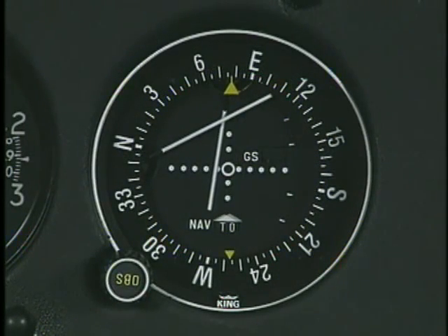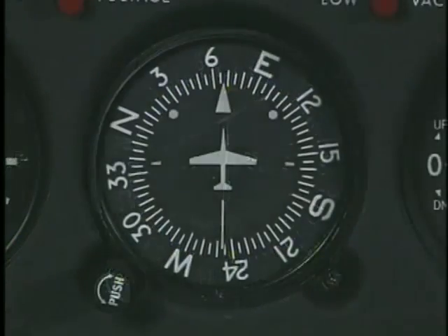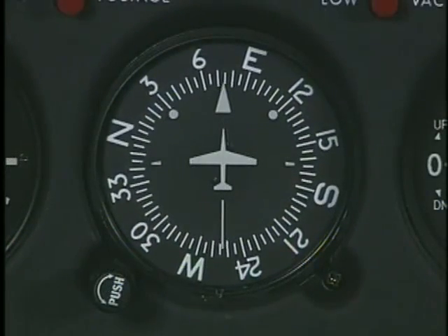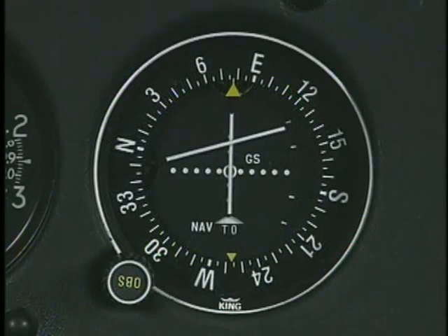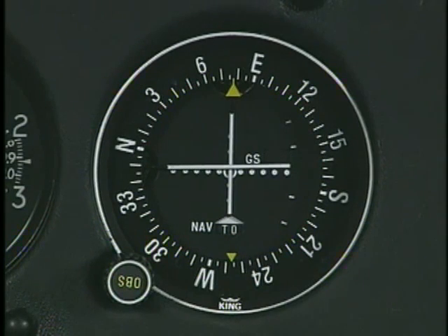Your clearance for the approach means you are expected to intercept the final approach course and fly the approach as charted without a further clearance. However, at a tower-controlled airport, this is not a clearance to land from the approach.